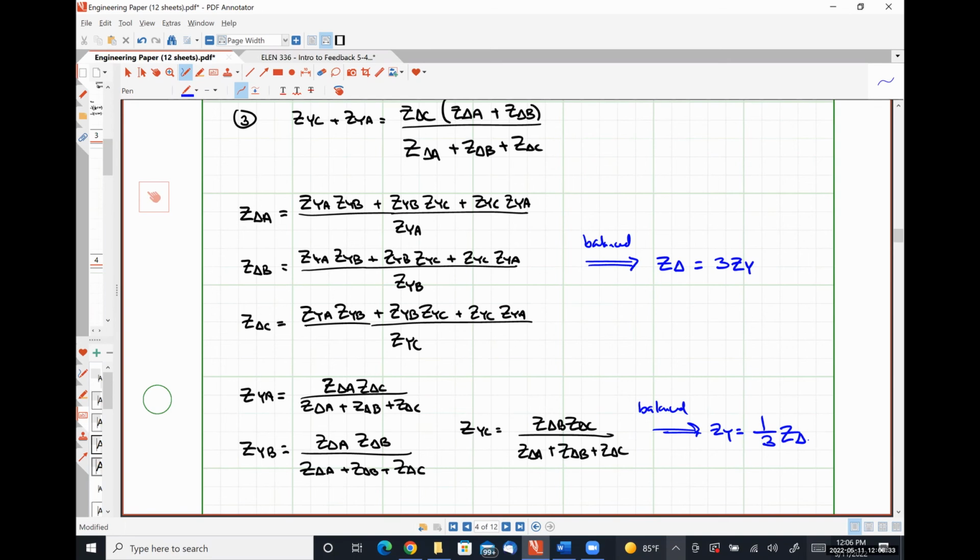So this is how we're going to be able to transform any balanced three-phase system into a YY system, right? And actually, we've developed the rules for making any three-phase system, regardless of whether or not it's balanced, look like a YY system as well.